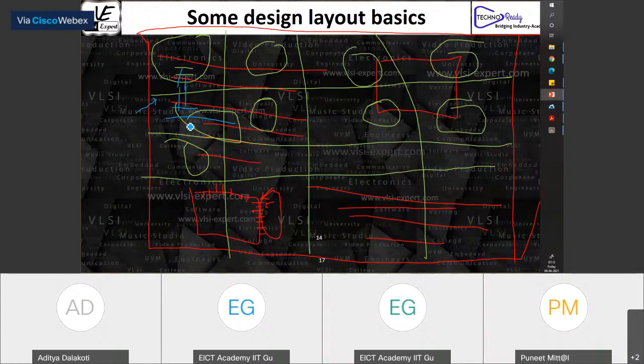In the last stage, which is the detailed routing stage, it is able to actually create those wires. The actual physical mask of those wires is created. When that happens, there are situations where, suppose this wire extends like this, the minimum edge DRCs are not met. Then it has to do further optimization to fix these issues.